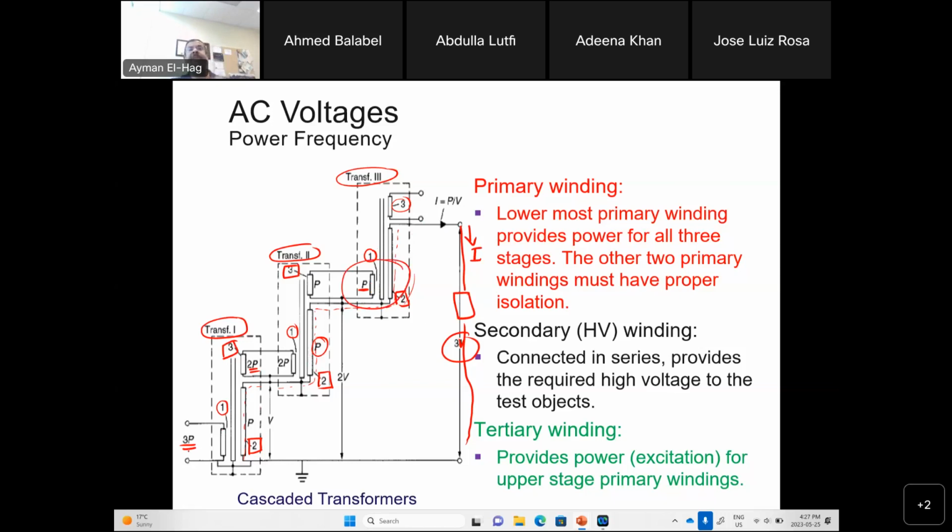The third one has 3 loads. So it has to supply the load and, through it, the other 2 transformers. So the other transformers are considered as a load for it. So the power rating of the first transformer has to be 3 times the rating of the third, and the second is double the rating of the third transformer. But other than that, it's all exactly the same.